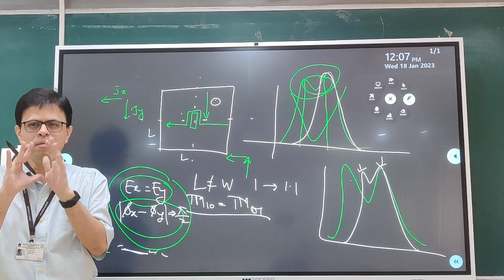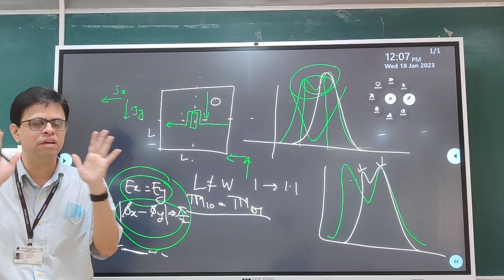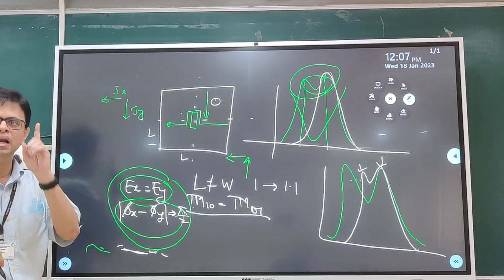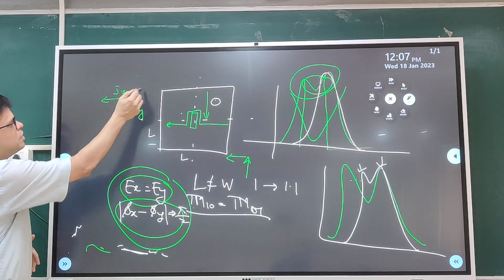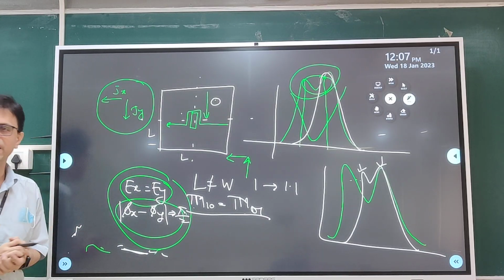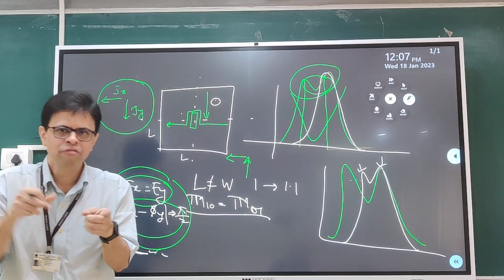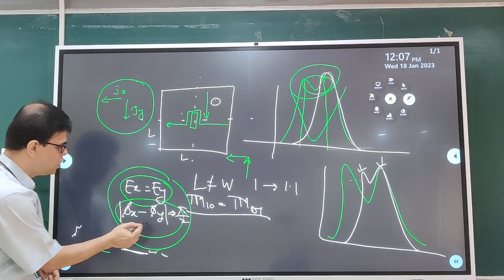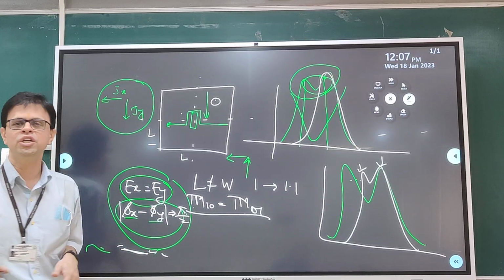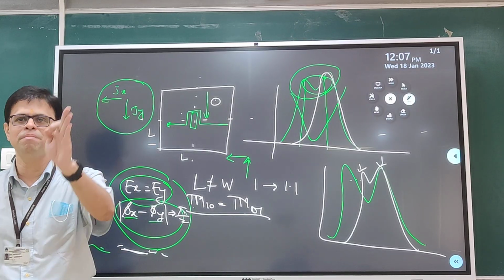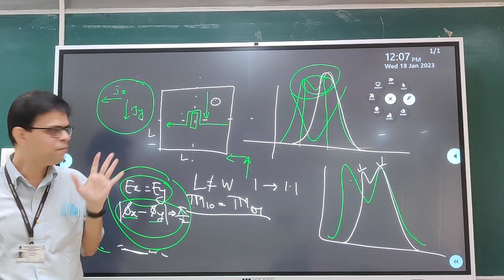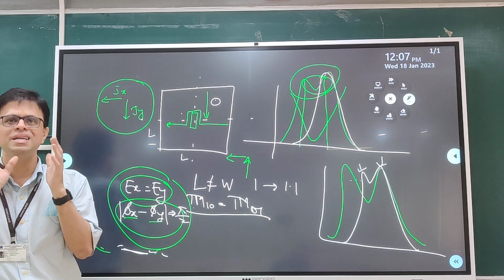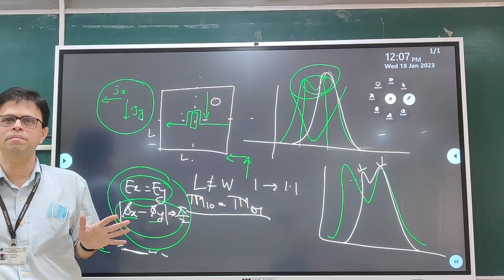So you have a CP radiation. See, this point that optimum frequency separation is something very important to understand. That optimum separation leads to proper distribution of Jx and Jy in terms of amplitude, which will effectively give me Ex and Ey, as well as that separation also ensures the phase condition is satisfied within pi/2 radians. So this will give me a CP response using a single feed and a simple slot cut patch.